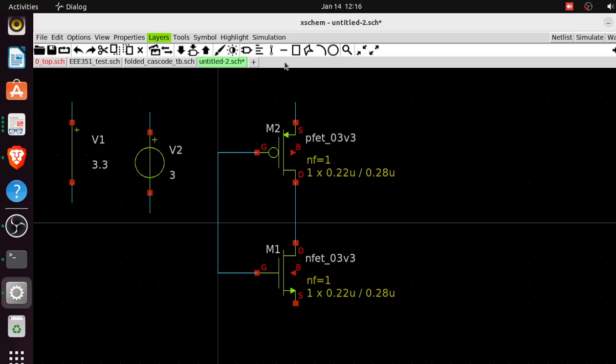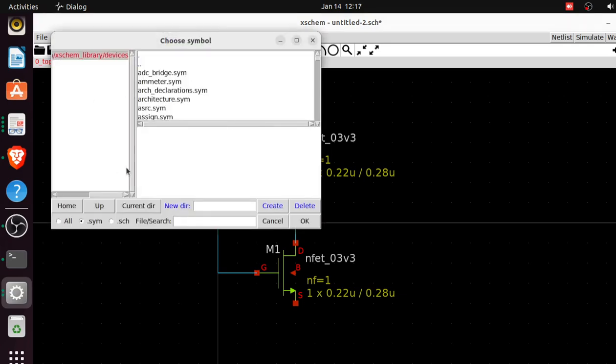The label is also a component, an object. So for any object, you go to where you select components and pick the object, pressing Insert. The label pin is not part of what you're going to be fabricating. It's just going to be used for simulation, that's all.